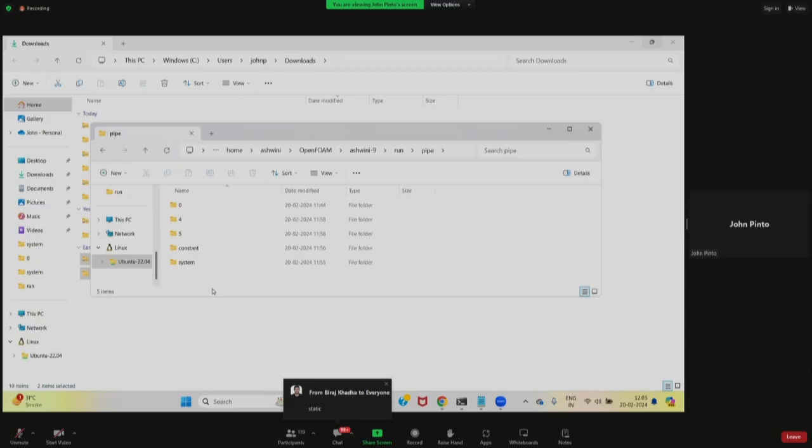So to avoid ParaView using that 0 folder, we rename 0 to 0.orig. So ParaView does not see the 0 folder, and it will show you only the mesh, and that error is removed. Now, once you have your mesh completely ready, that means your inlet, patch, wall, everything is coming properly, you are ready to go to simulation. Now you have to specify the boundary conditions. So the next step is to rename this 0.orig folder back to 0, so that it gets used in the simulation, and then provide the appropriate boundary conditions for every patch.